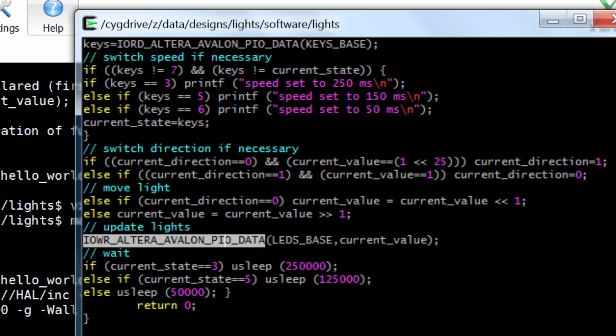So that's 2 to the 4th plus 2 to the 3rd, which is 16 plus 8 is 24. So if you write the value of 24, and the base address is hex 0, that will put a 9 on hex 0, which is the rightmost hex digit on the board. You guys with me? Make sense? That's assuming that you want to put a digit there.